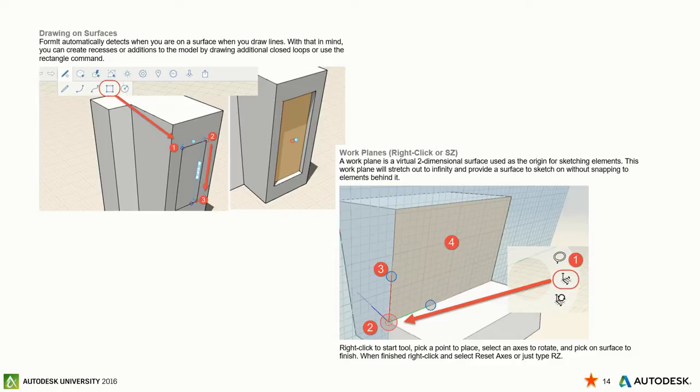Even though the axis is on that surface, you can still pick points through the grid. So if there is a point in the back of where that surface is, you can still align to it. So your object snaps are still free to go wherever it is. It just knows that, hey, when you draw that line, don't go off into that back point, stay on this surface. Okay? That's one of the reasons why they came up with the work plane tool, is just to give us more control over that.